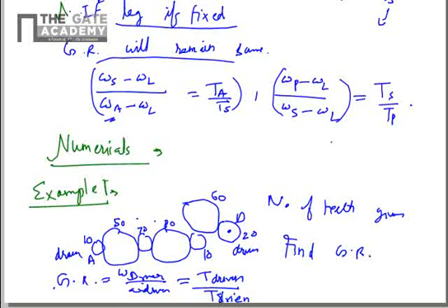The intermediate numbers don't matter. So there is no need to get confused by such a complex chain and so many numbers of teeth given. We just have to consider the input and the output. So driven has 20 teeth and the driver has 10 teeth. So the gear ratio is 2.